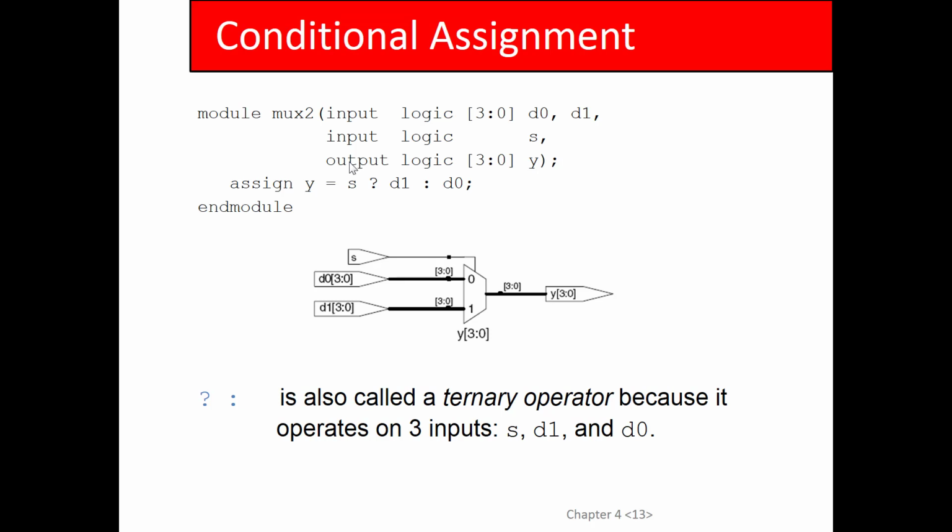For example, if you're making a CPU, you're going to have an ALU in there. But you want to be able to use that same ALU for different instructions, which may get their inputs to the ALU from different sources. And in order to implement that behavior, to steer the right operands into the ALU depending on what instruction you're executing, you have to use muxes. So this kind of statement shows up a lot in Verilog, especially if you're doing architecture or microarchitecture, processor design. Very common, so you want to be comfortable with that. Any questions about that?